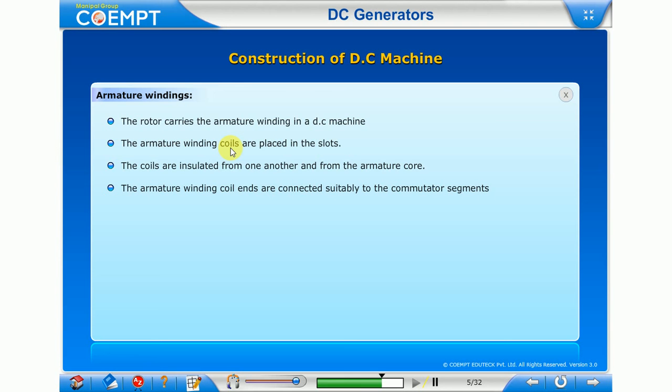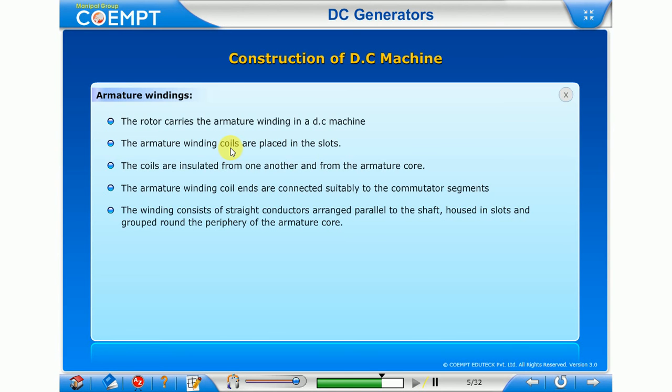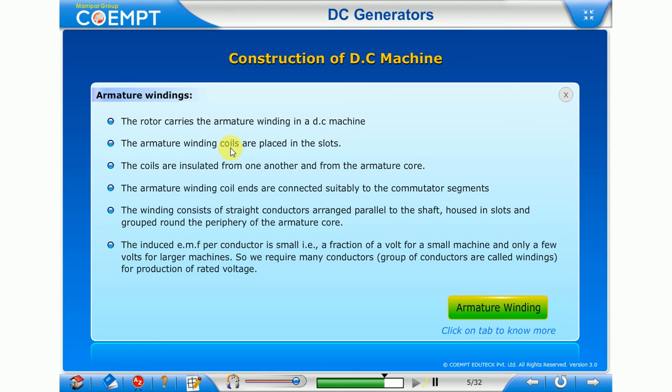Compensation windings. Compensation windings are connected in the same way as the interpole windings, but they are located in the axial slots of the field pole shoe. Compensating windings are used for large DC machines to neutralize the cross-magnetizing effect of armature reaction.